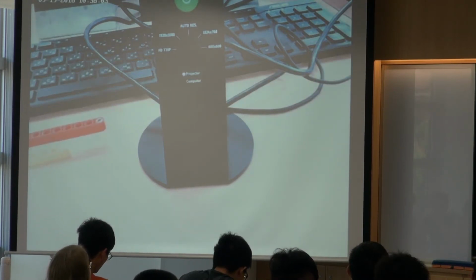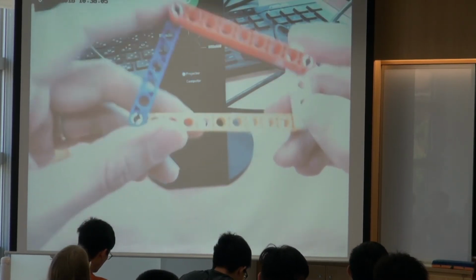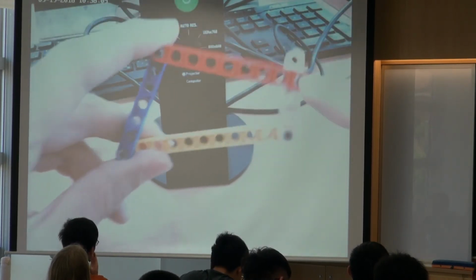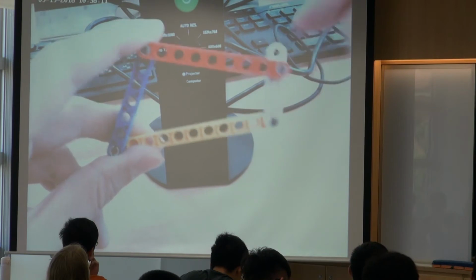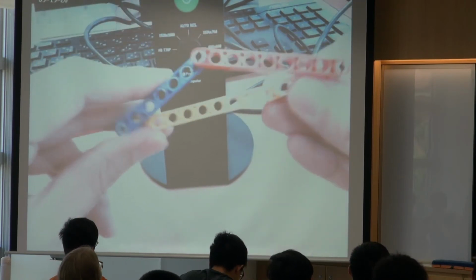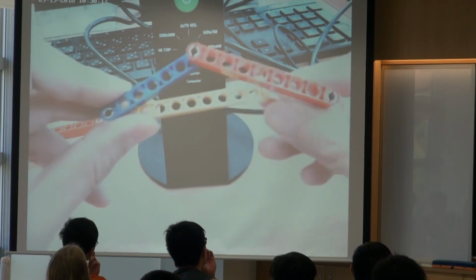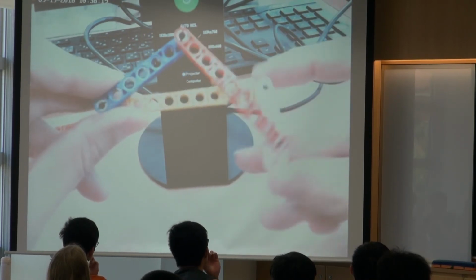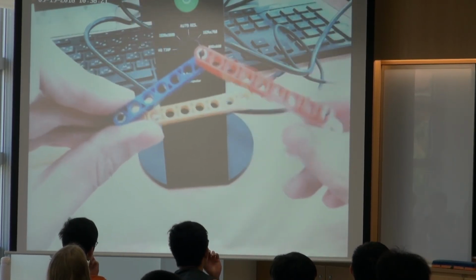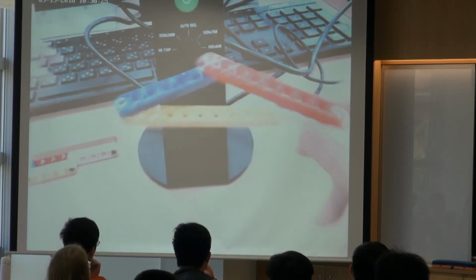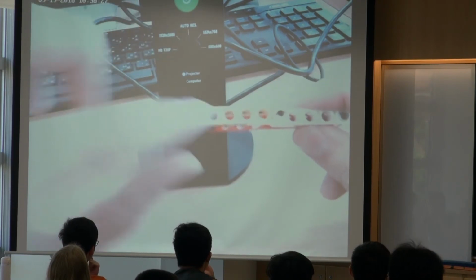So previously, in another situation, this one is not going to become a line. I shifted the white one by one grid. So this one is not going to become flat, no matter how you rotate it. So this one is a Grashof mechanism. This one is a Grashof neutral.